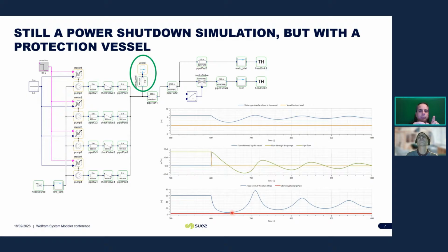Yes, the vessel behavior on the first plot can be seen. We can see that the liquid level decreases as water is supplied. Yes, and then the system reverses and the vessel refills again. Well, this is a cyclic movement after the pump stop. We can also observe that the vessel is correctly sized because we can see that the vessel never empties. Well, it's represented by the orange zero line, yes, there.